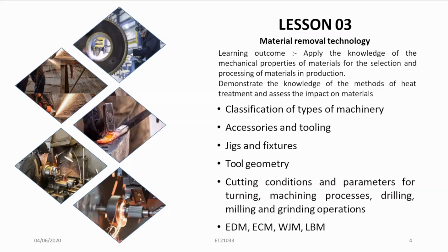So when you consider the tool geometry, the angles and edge features decide the chip flow, also heat and the forces and the finishing of the surface, and also it decides the tool life. So when we use tools in the manufacturing removal processes, basically we have to consider the tool geometry. Then let's move.